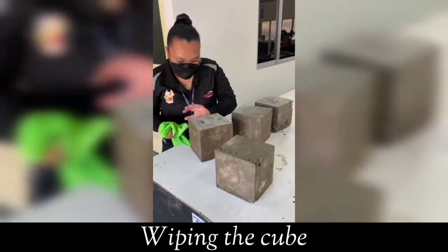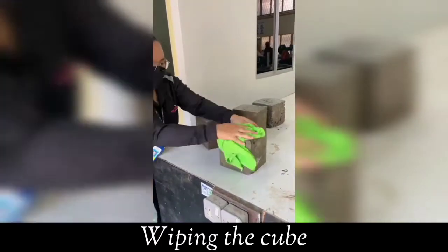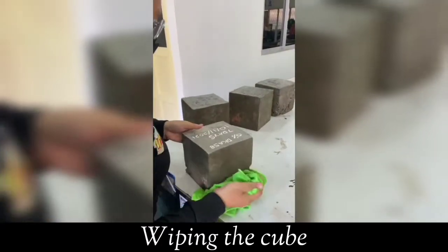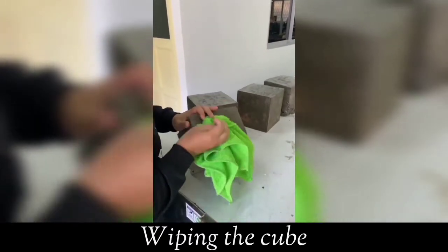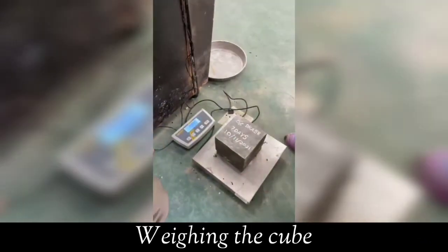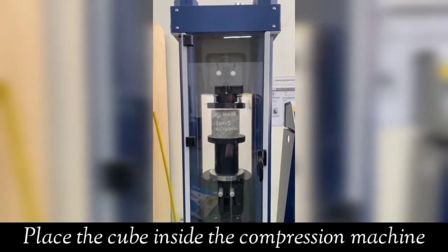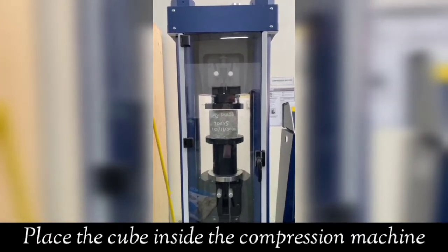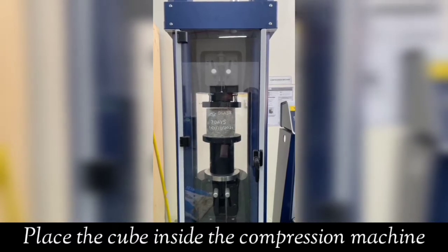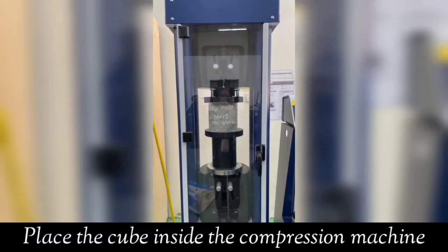The first specimen, which is a cube without any additional chemical mixture, is taken from the water after 7 days curing time and excess water is wiped off the surface. The cube is weighed on the weighing balance and the mass of the cube is recorded. The cube is placed in the machine in such a manner that the load is applied to the opposite sides of the cube cast, and the cube is aligned centrally on the base plate of the machine.